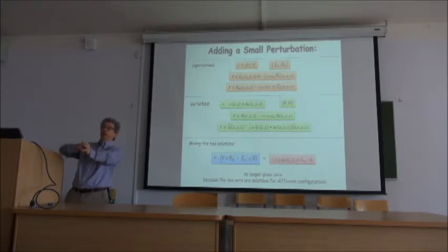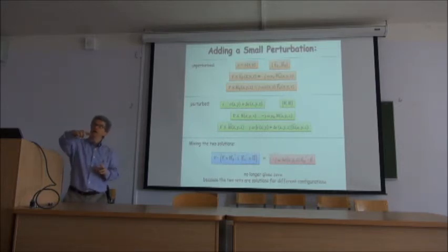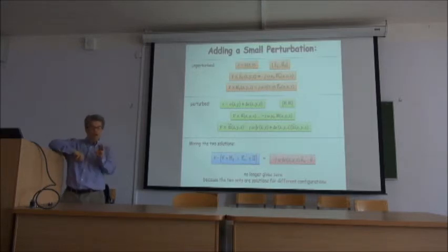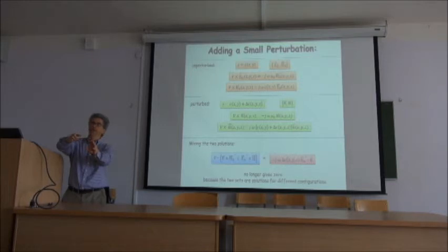I have the original, like just a cladding, or for instance, you can picture a glass. And then I bring another channel waveguide here that has a little higher refractive index than my cladding. So this is one type of perturbation. Another possibility is that I have a waveguide here, and I write a little grating in there. I write a periodic modulation. So I have my waveguide unperturbed, and then I write a little grating in there. So this is a perturbation.